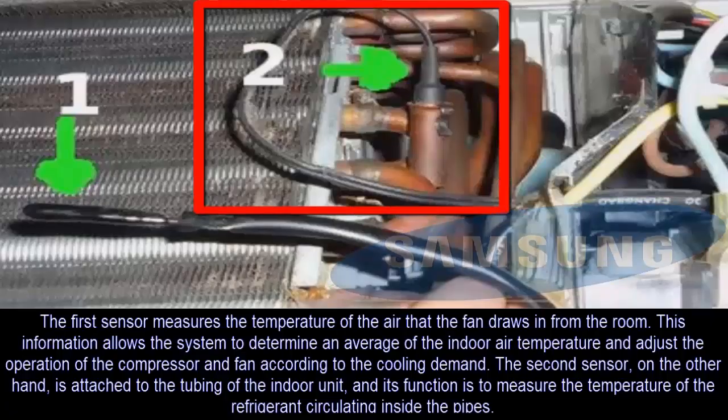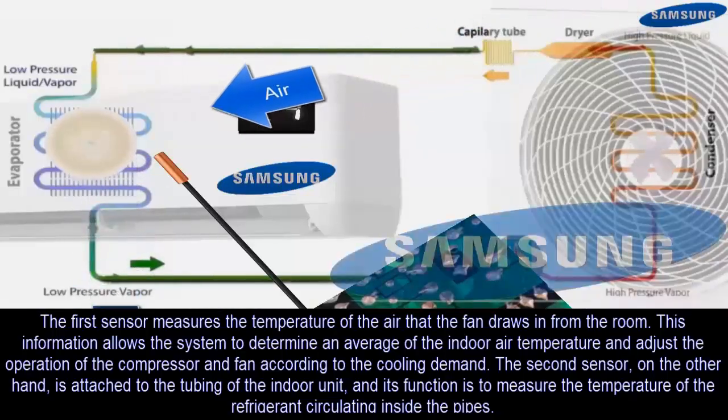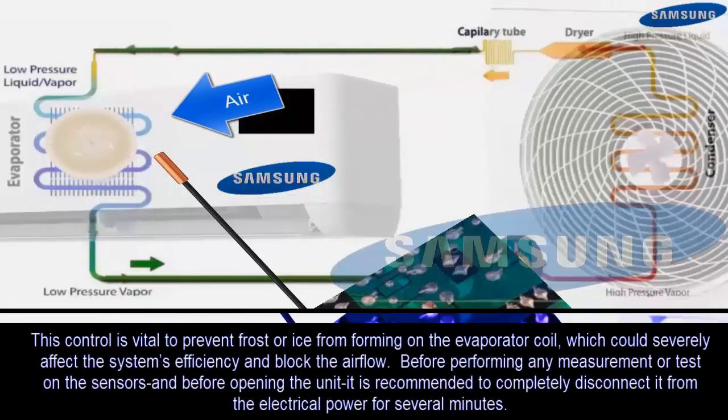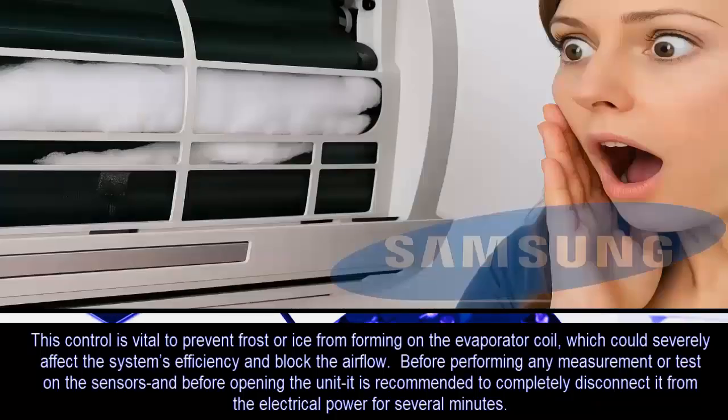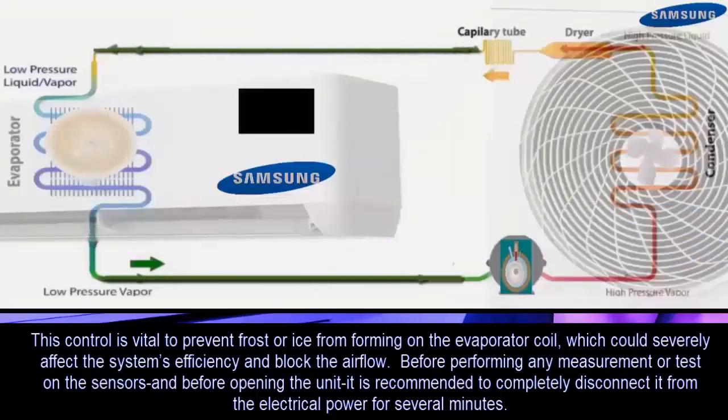The second sensor, on the other hand, is attached to the piping of the indoor unit, and its function is to measure the temperature of the refrigerant circulating inside the pipes. This control is vital to prevent frost or ice formation on the evaporator coil, which could seriously affect the system's efficiency and block the air flow.